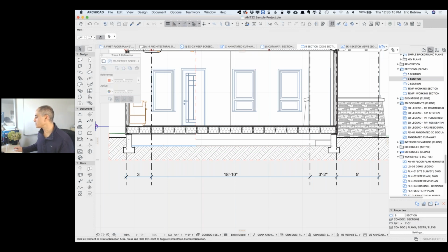After working on it, I should save a view, otherwise it comes back to the saved one. Yeah, when you double click on a view, it goes to a particular context, certain layers, certain orientation in 3D, etc. If you change the layers and you want to retain that, you should either redefine the view, if that's what you want, or create a new view and save that. And you can create as many views as you like.